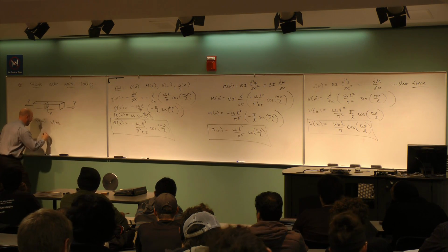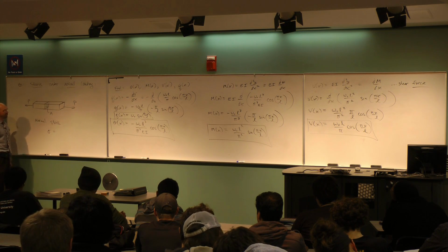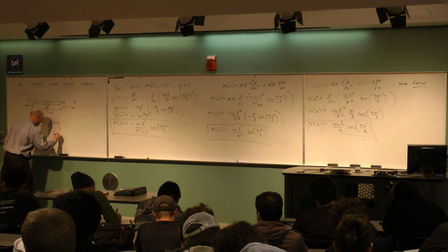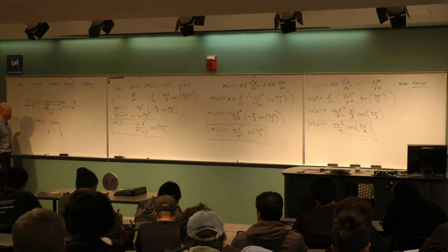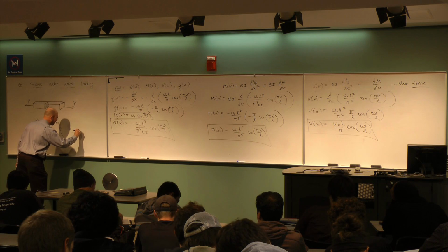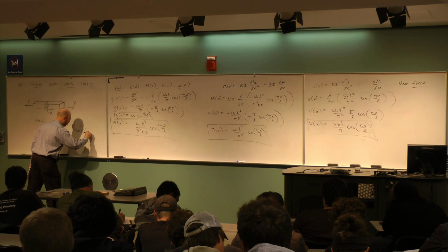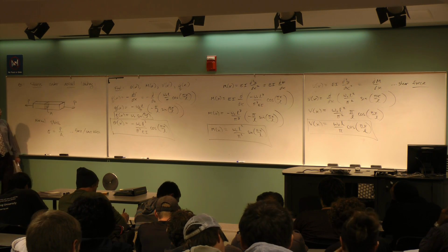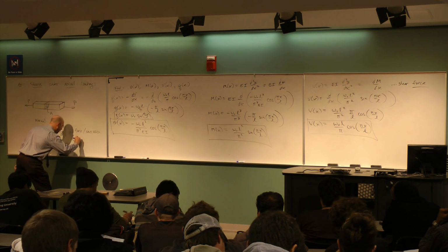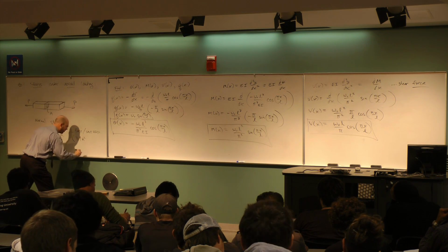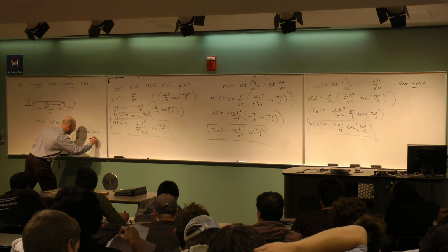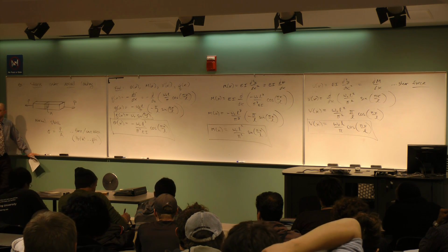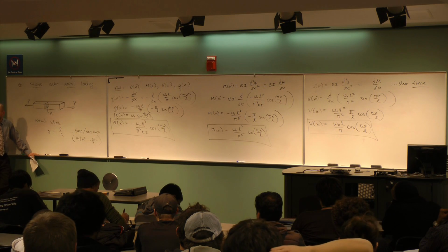Okay, and so it turns out we use the Greek letter sigma for stress. And what it is, it's the intensity of the force. It's the force P divided by the area. Okay, so this is force per unit area. So if I am in English units, this is pounds per square inch, which is what we also call PSI. What else is measured in PSI? Pressure. Air in my tire.